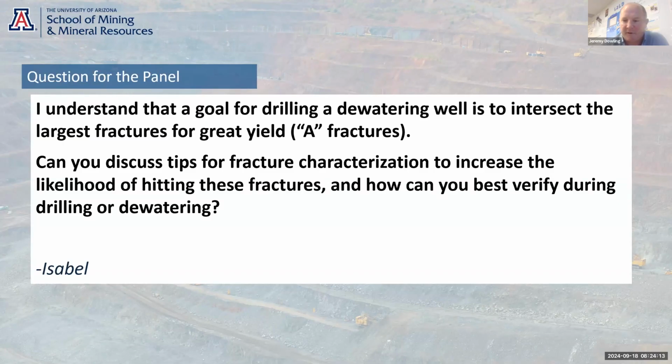Whereas if the flow rate rapidly decreases, maybe the fractures are very localized, and a pumping well would be less sustainable at the location. So there's a lot of different practical testing that can be done during the drilling of the pilot hole to try and understand the location of the fractures and how interconnected and productive they may be if you proceed with drilling and constructing a pumping well at the same location.